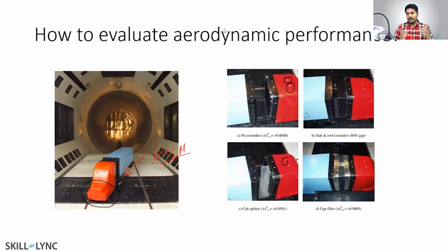If the mesh is identical, all the results boil down to what governing equations you're solving, what algorithm you're using to solve, and what type of turbulence modeling schemes you use, right? So you can do a validation study, and that is the first thing that everyone needs to do. You need to validate your CFD code, and then based upon the validation you can figure out that, okay, if I'm able to validate an external flow problem at this Reynolds number, then for that same Reynolds number, if I modify the geometry, most likely I'm going to get a very close answer. That is why this is being done.